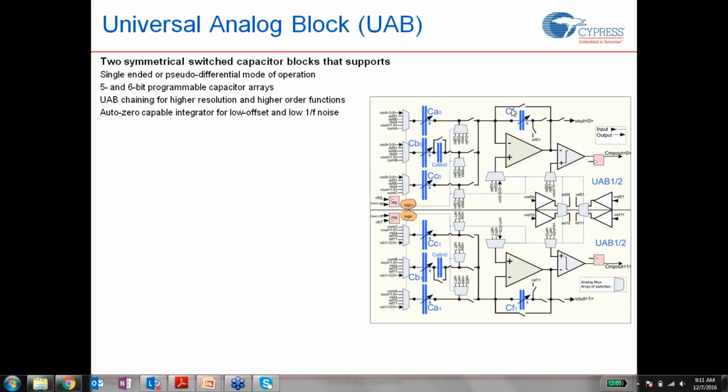You have other use cases where you do not switch the feedback capacitor, and only switch the input capacitor. Then what you're doing is controlling the charge flow, but accumulating it on the feedback capacitor, which is equivalent to low-pass filtering or an integration kind of nature.